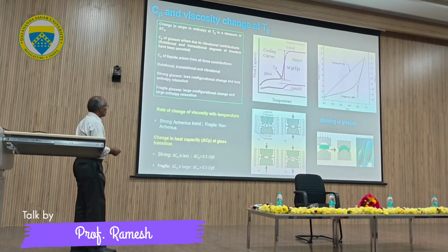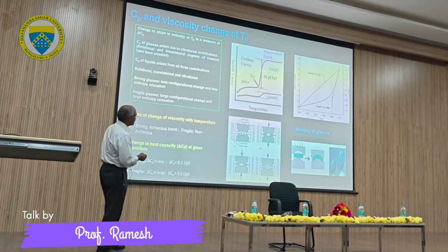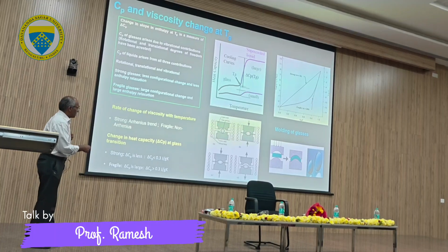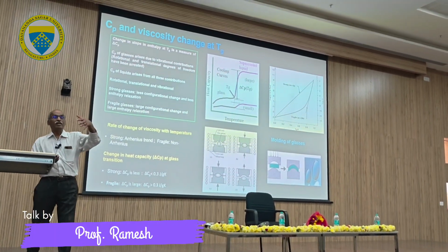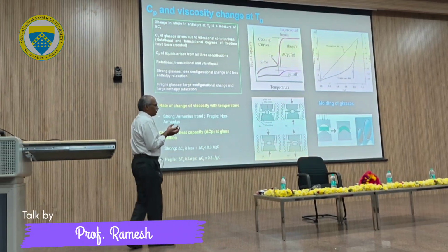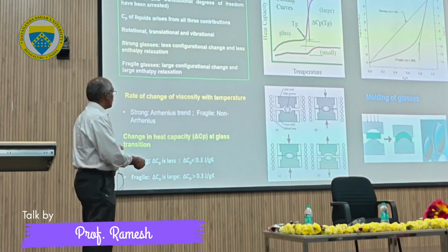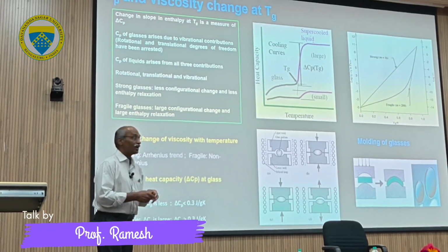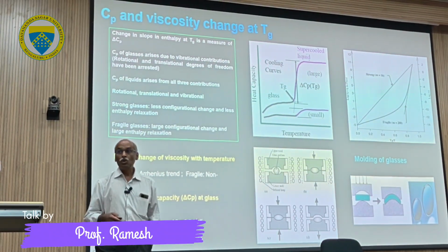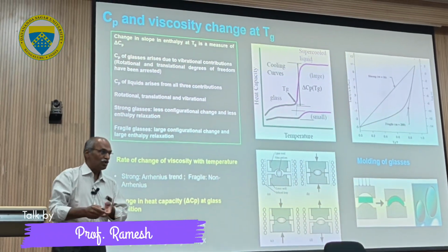So I said at this point, the glass transition temperature, the glass softens. Many lenses are made this way, right? You take the material to the glass transition temperature where it softens, and then you make a mold. For example, you want a lens shape, you make a mold of that and put some pressure, and you can change the shape. This is how companies make lenses. You don't have to go to the melt state to make a shape, or grind them. So it's an